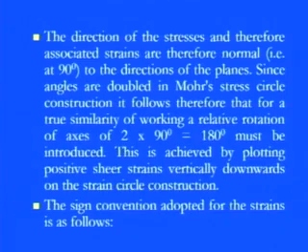the y axis. And it should be noted that the angles given by the Mohr stress circle refer to the direction of the planes on which the stresses act. So you see, not the direction of the stresses themselves. Whatever the stress directions are, we are not concerned with them, but only checking at what angle these stresses are acting. The similar things which we are going to discuss here apply also to the strain conditions,